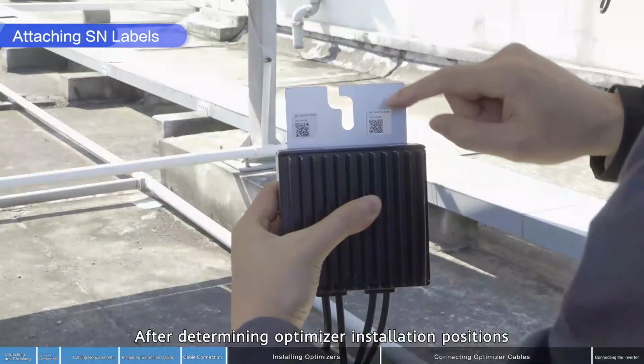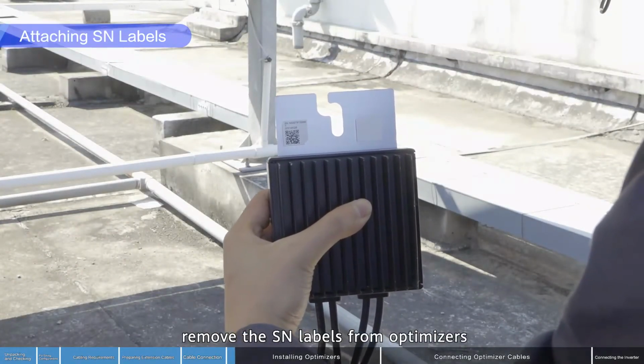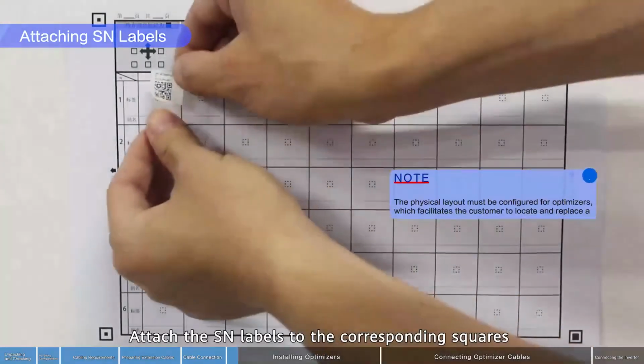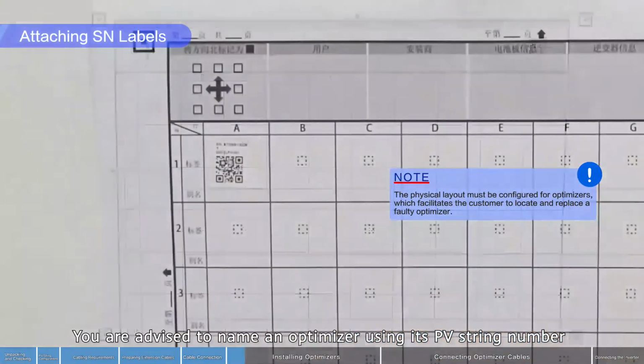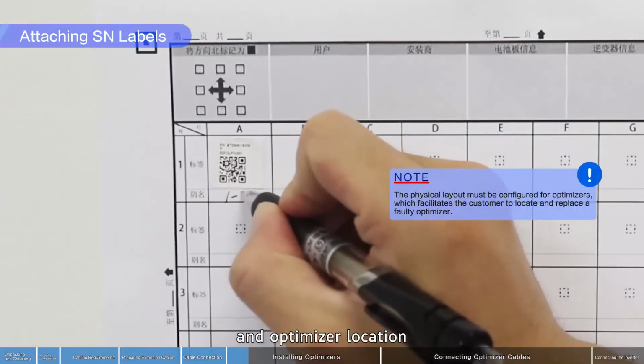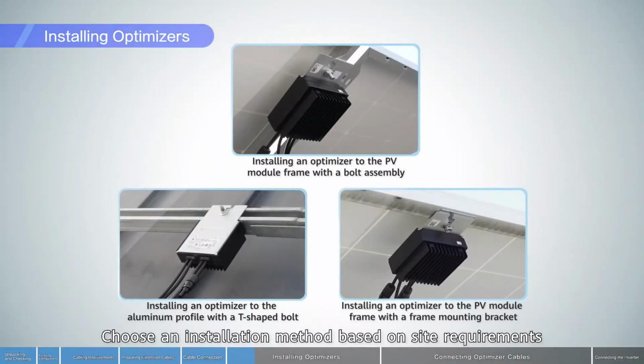After determining optimizer installation positions, remove the SN labels from optimizers. Attach the SN labels to the corresponding squares in the physical layout template. You are advised to name an optimizer using its PV string number and optimizer location. Choose an installation method based on site requirements.